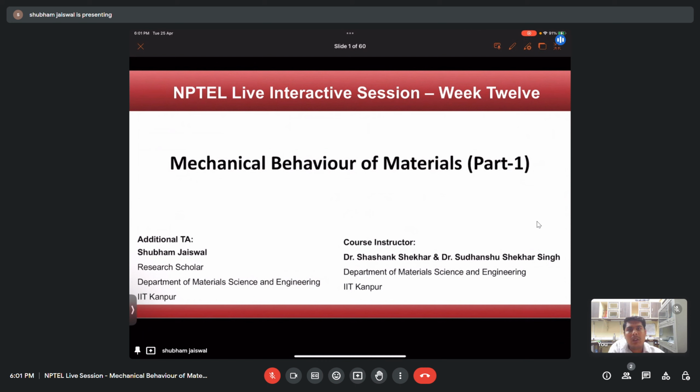So last week we began with the concept known as hardness testing. What is hardness testing, or what do you mean by hardness? Hardness is a measure of a material's response, or we can say the resistance to a localized plastic deformation on the surface. Why do we need hardness if we have other methods like tensile testing?